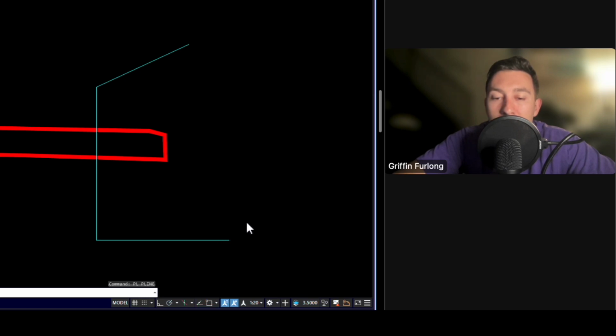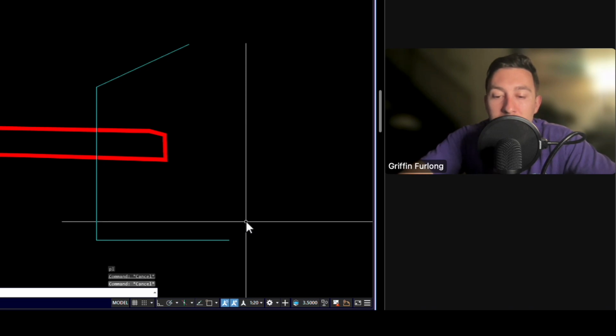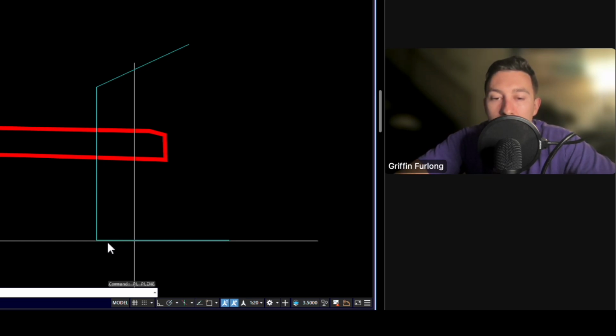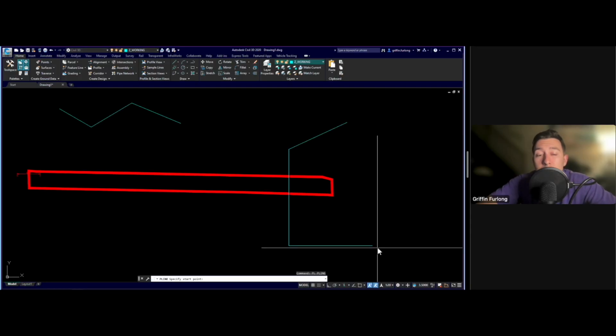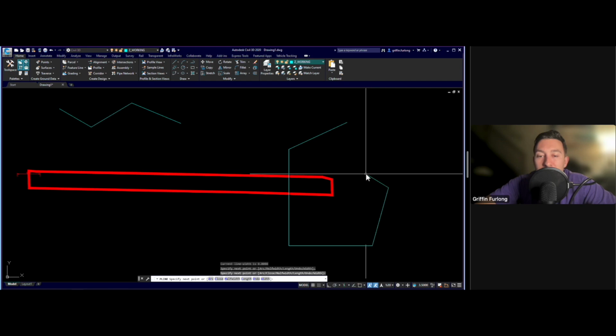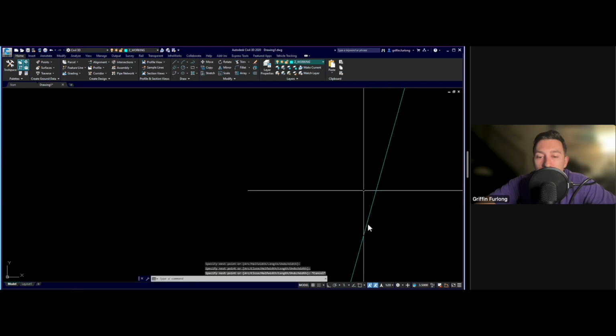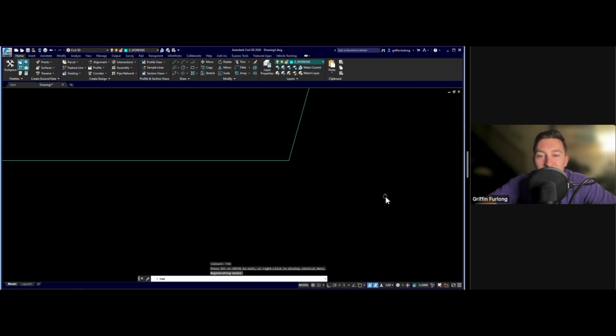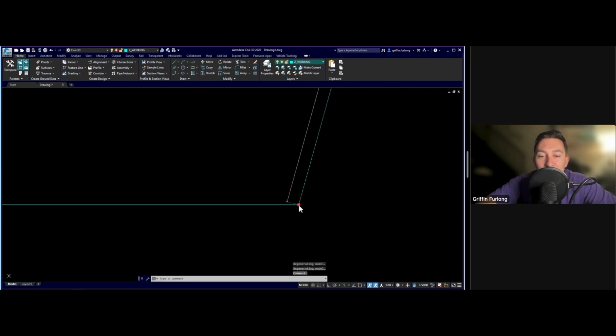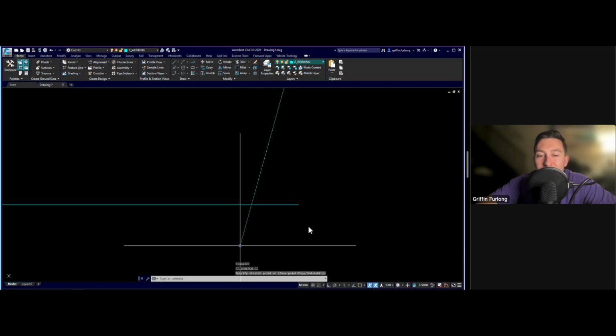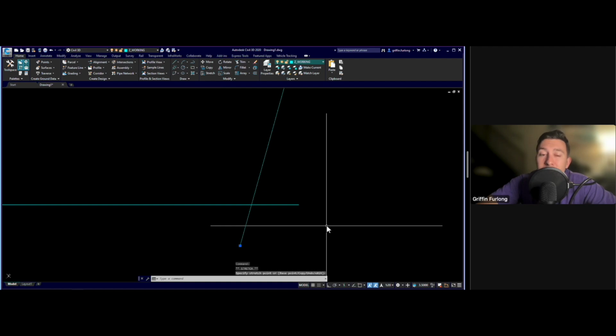Now notice how if I turn this guy off and do the same thing here with polyline, I'm not getting any green box anymore. That ends up becoming a really big problem if you're a drafter and you think that you're close to this endpoint here, and then you start drafting these lines, and then lo and behold, you end up realizing that these lines aren't exactly touching, which, man, I got really close there, huh? But let's say you're drafting, and you're trying to get something into construction document form, and you have a whole bunch of lines like this crossing over and not touching, you're going to get a lot of false dimensions there, and in my eyes, that's pretty sloppy CAD work.